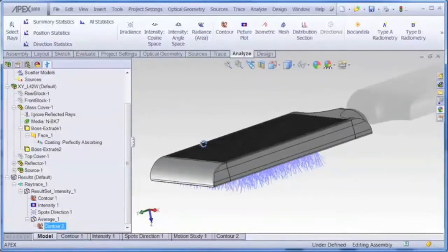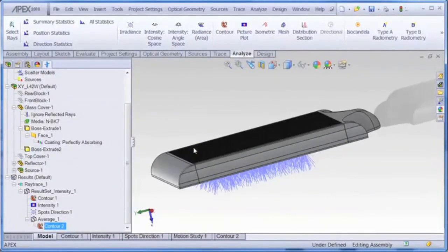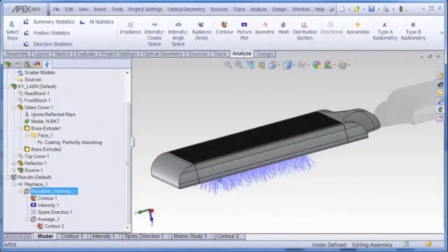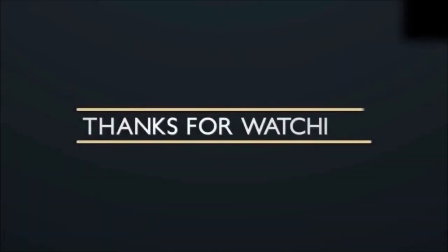So in summary, what we've looked at today is how to take our engineering drawing, turn that into a design that has the necessary information to perform a ray tracing, and then we've done some ray tracing and analysis on the design. Also remember that there are the tools available to you, such as the ignore, either to ignore geometry or ignore particular ray directions, that can allow you to speed up your analysis without in any way affecting the accuracy of it.